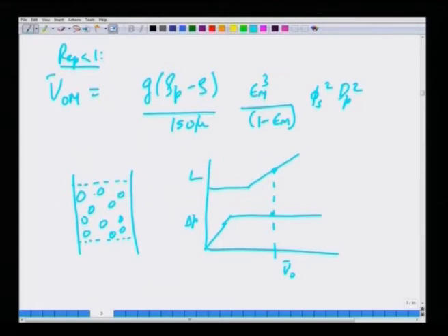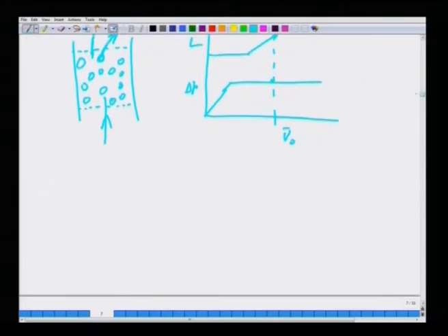fluidization velocity in this regime is such that, because during fluidization gas is continuously coming in and going out, while the gas is going out we should take enough care that it does not entrain particles along with it, because the whole point of our fluidized bed is to keep the particles inside the bed in an animated state of motion to enhance mixing and improve transport properties. So, how do we check whether the particles will entrain or not?